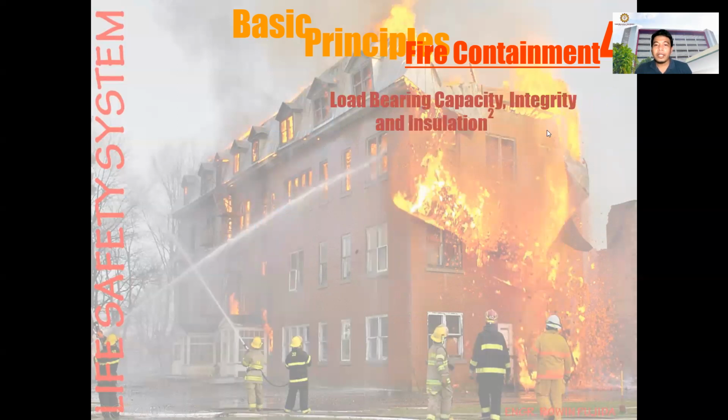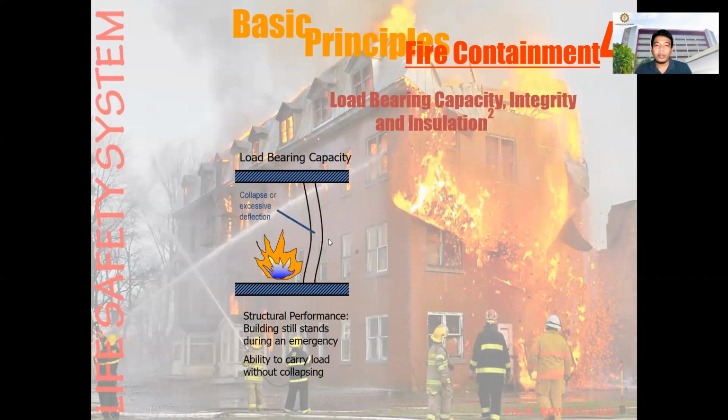So, load bearing capacity, integrity, and insulation. Load bearing capacity: to resist collapse or excessive deflection of the structural member. The structural performance, so the building still stands during an emergency. Ability to carry loads without collapsing.